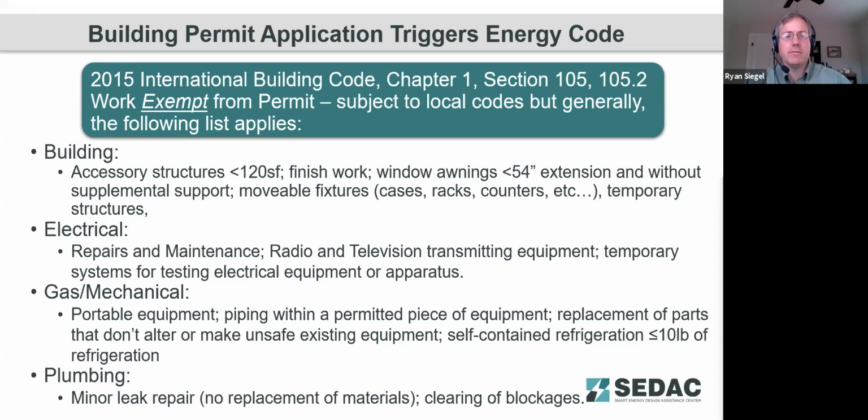lists several types of work that are typically exempt from permit applications. However, please go ahead and check with your local jurisdiction, whether that's a municipality or county, and they can provide you some further guidance because they may have exempted some additional items beyond what the International Building Code calls for. They also may require permits for some of these things that are exempted by the model code.